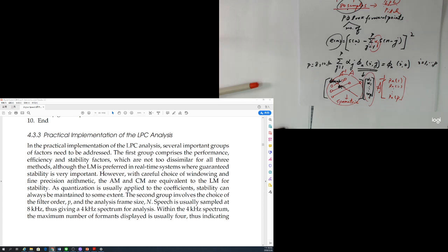In linear prediction coding, inside the speech frame, each signal is predicted by a linear combination of the previous p samples to predict your current sample. Because inside this speech frame they use the same coefficients, they try to find what coefficients can minimize the prediction error.